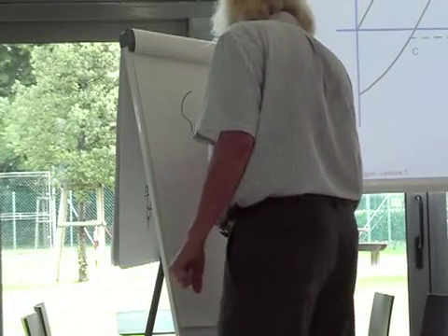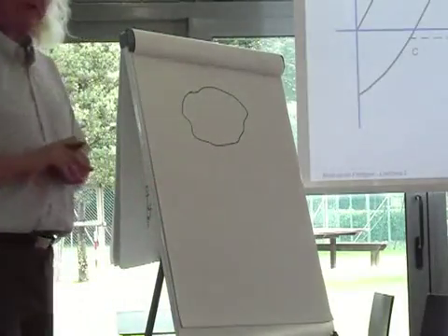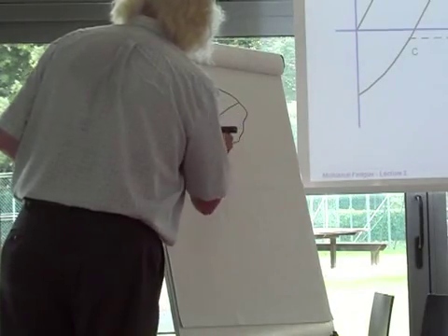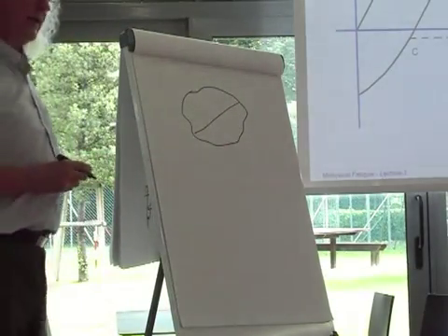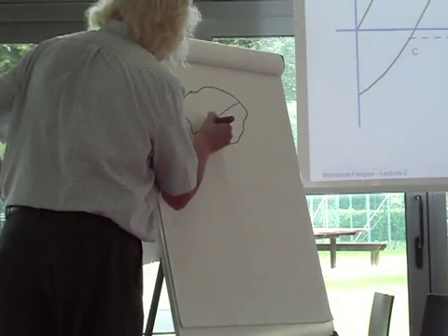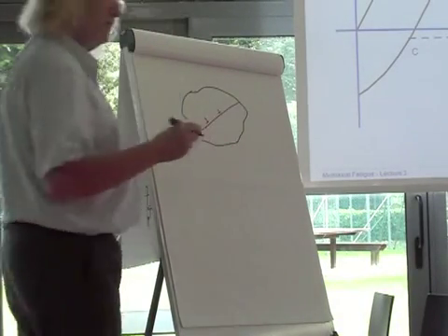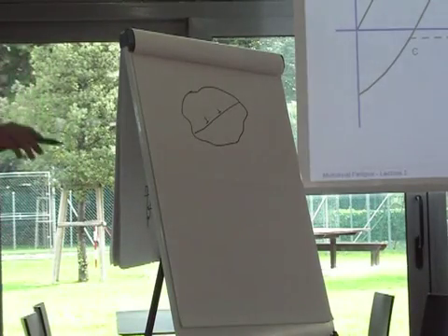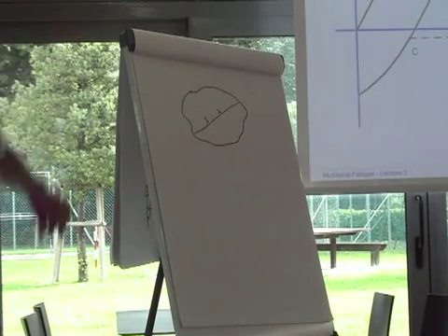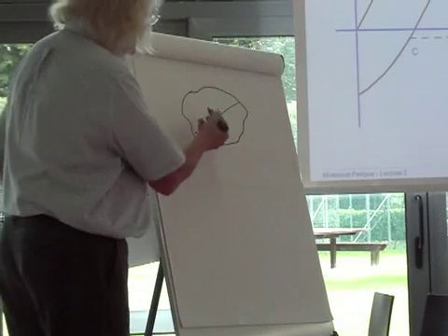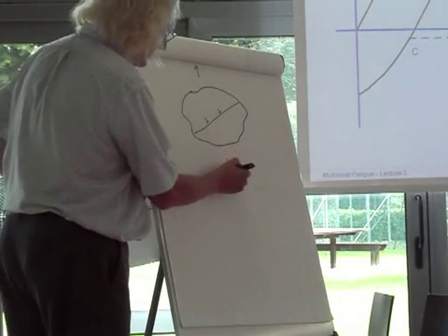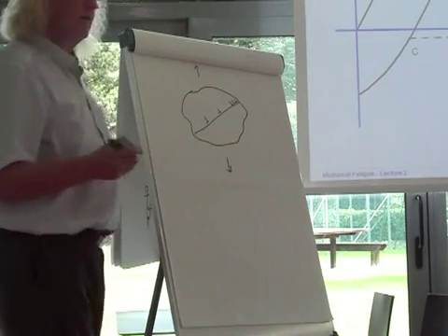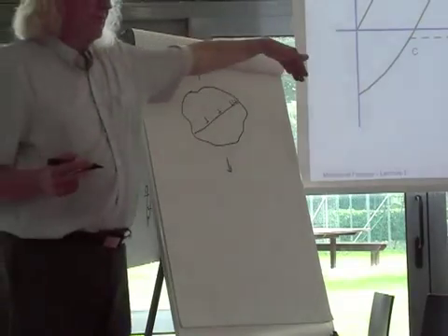So I have a little metal crystal. Right? So there's one of those crystals. And it will have a slip plane acting on that crystal. And on that slip plane, there will be some little dislocations, maybe like that. Right? A whole bunch of them, but there will be some dislocations. Right? And that's the natural state of the material. And now I pull this, right? And when I pull this in tension like this, then these dislocations will all pile up on one side. Fine. And maybe I get some plastic deformation.